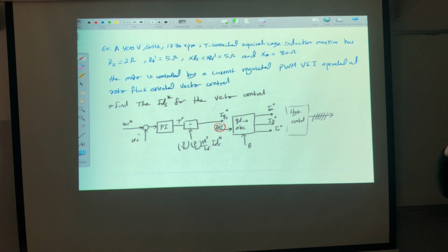I will discuss that after. Now, the question was, why am I not using the hysteresis current control before the transformation? Before the transformation, in which reference frame am I? QD, in the synchronous rotating reference frame. Any signal that rotates at the same speed is seen as constant. So if the reference is constant, why would I use hysteresis? There is no reason to use hysteresis.